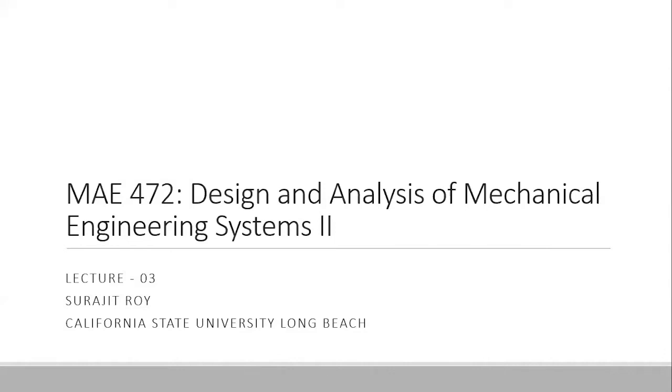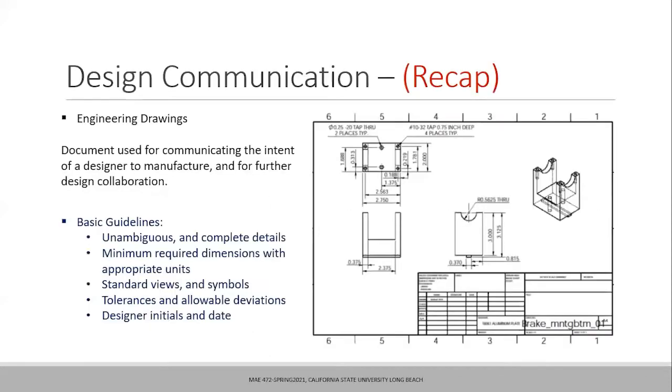Yes. Good. So just a recap, as we were discussing, I would like you guys to prepare a component drawing, which basically should have the front view, the side view, the top view with all the information in there about fabrication of that part, along with an isometric view at a corner, which can be at the bottom right, top right, whichever space is there for you in your drawing.